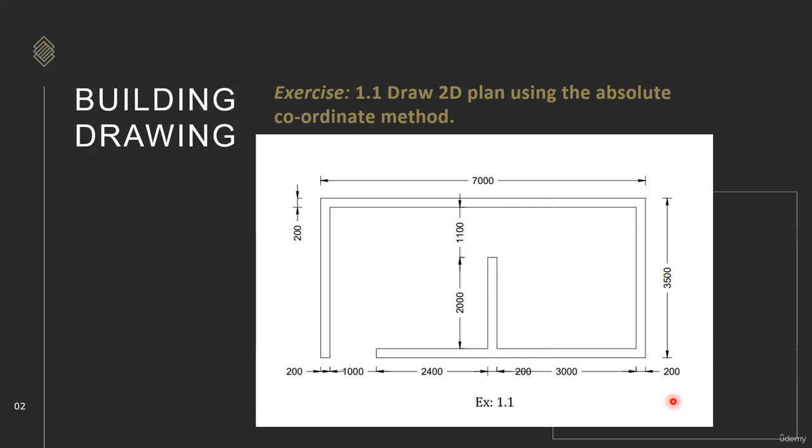If it is a load bearing structure, if it is not mentioned, in most cases we use 300 in the load bearing. In some cases we use 200, depending on the structure. If the span and all is more, in those cases we go for the higher thickness. If loads are less and only a single story building is there, in those cases we use 200 also. There is no issue. And the next one is frame structure.